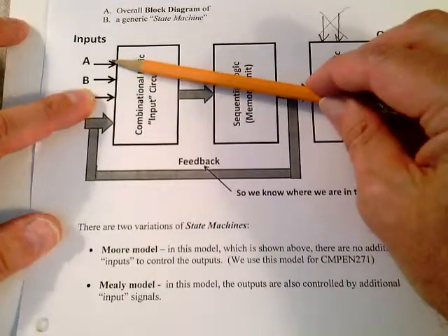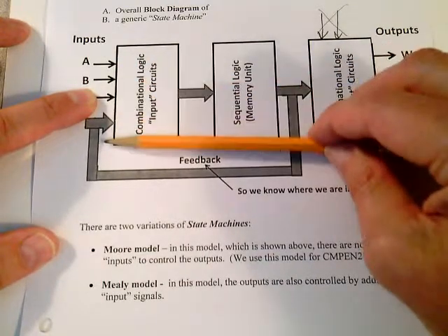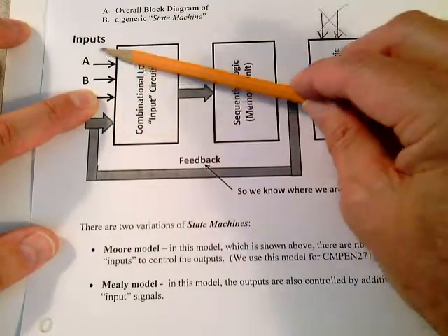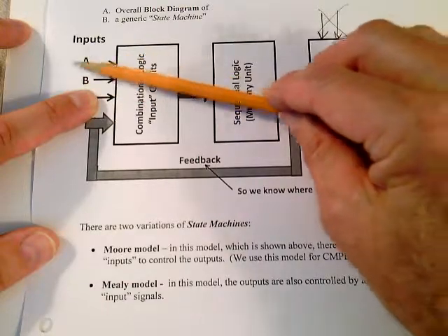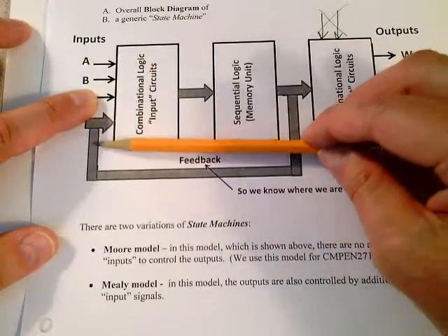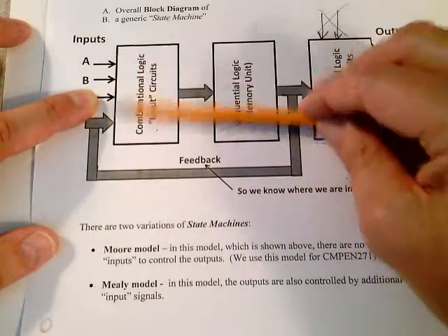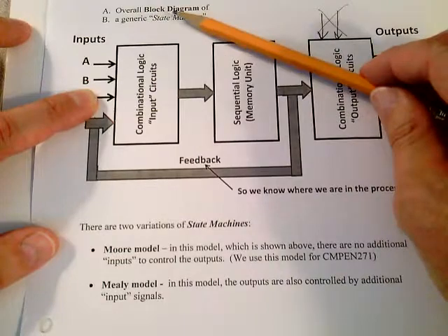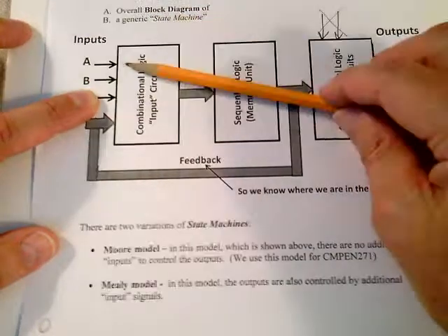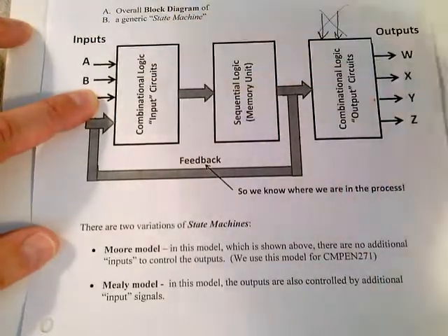So all you do is count the total number of inputs you have in your present state table, which include these discrete external inputs plus your feedback terms, which is how many flip-flops you got. Now your total number of inputs will tell you what variable K-map you're using: a 3-variable map, or a 4-variable map, or a 5-variable map, or a 6-variable map.